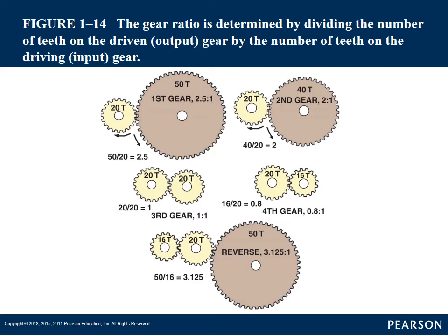Again, we'll talk more about direct drive, overdrive, and low gears when we get into planetary gear sets. But you can see where both gears are the same size, 20 teeth on each one. So 20 divided by 20 is 1, so we have the 1-to-1 gear ratio. The drive gear turns once, which means the driven gear turns once. That's a direct ratio. In our older transmissions before overdrive, this was always our top gear. Even in our first transmission that we talked about, our Hydra-Matic that was in our Oldsmobile, it had 4 speeds, but the top speed was 1-to-1. We did not have an overdrive.